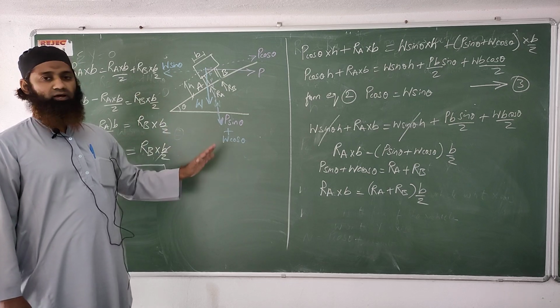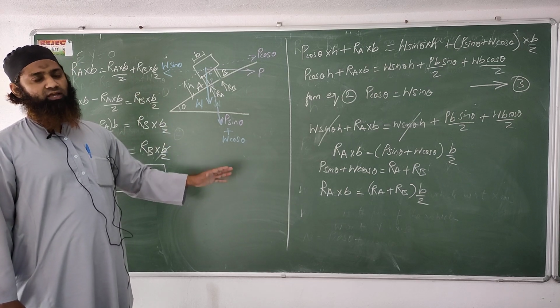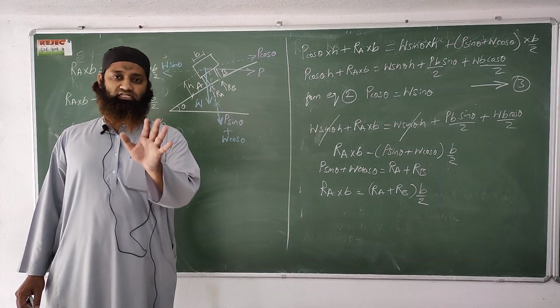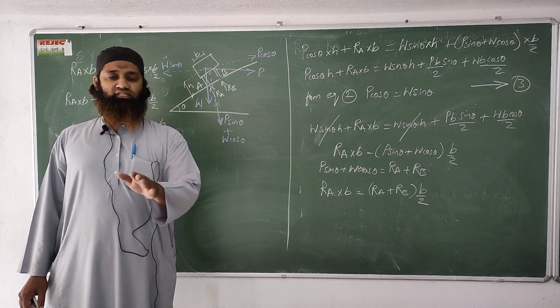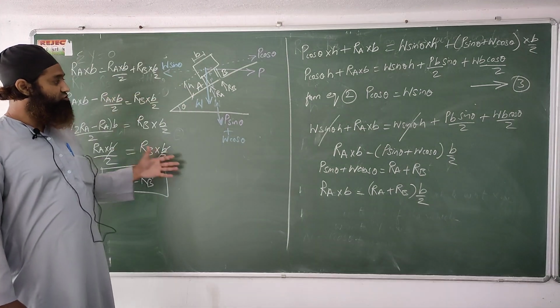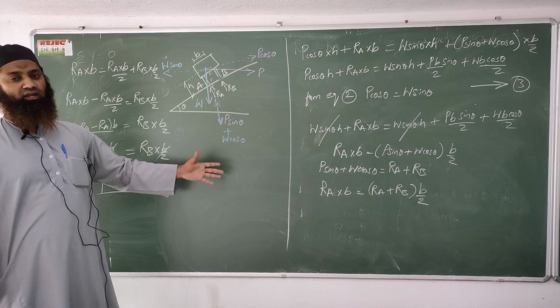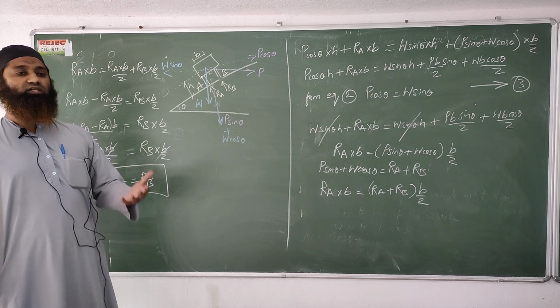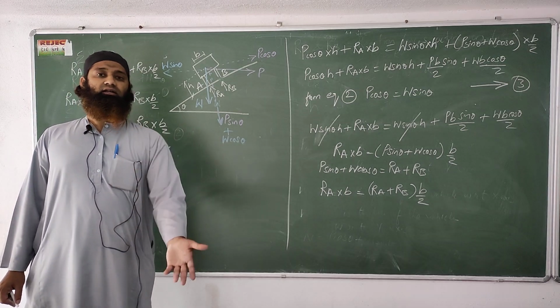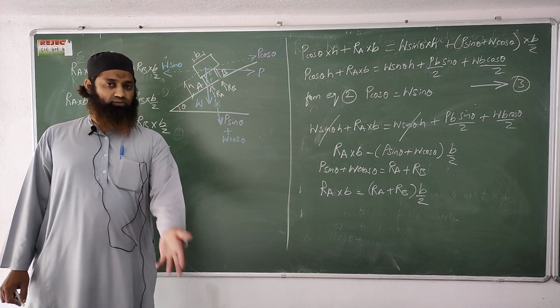So this is very simple, I believe. Equilibrium super elevation we have seen, where the two tires will have the same reaction forces when there is no frictional force acting on it, where the frictional force is 0. So here we have just solved this equation. In the next sessions we'll be seeing a problem, and other concepts also that are coming up.